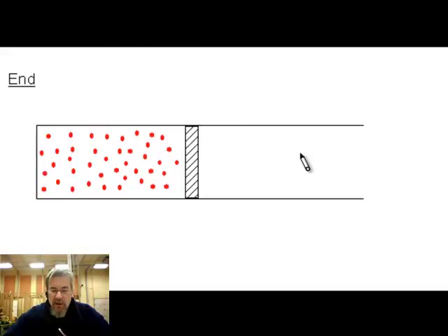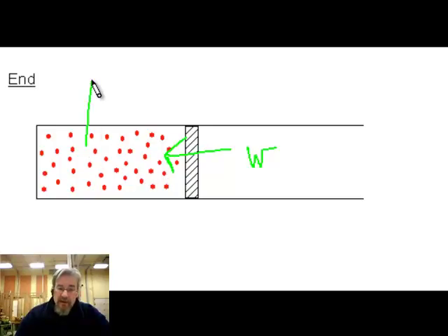We're compressing the particles into a smaller space, so the system is definitely gaining energy from the surroundings, because the surroundings are working on the system. As these little particles impinge on the piston, they rebound with more energy because the piston is moving into them, and that means the energy goes up. The total energy goes up. That means the temperature would have to go up unless there was a loss that matched it. And so energy has to go out to the surroundings. And if this is isothermal, Q and W have to match again.